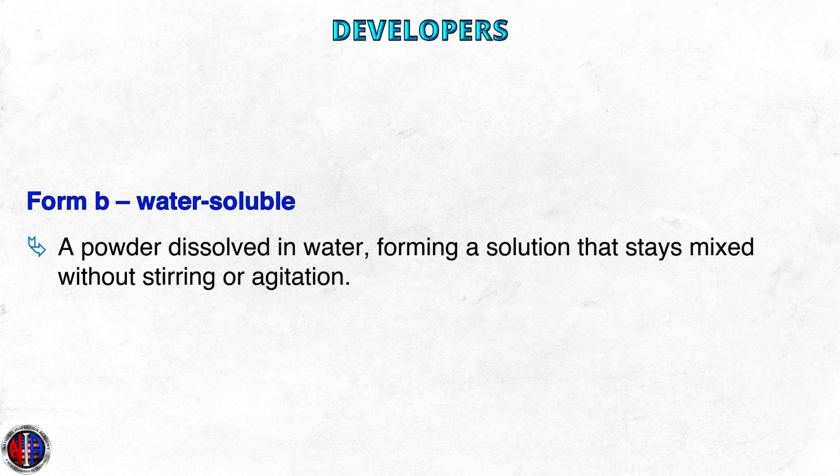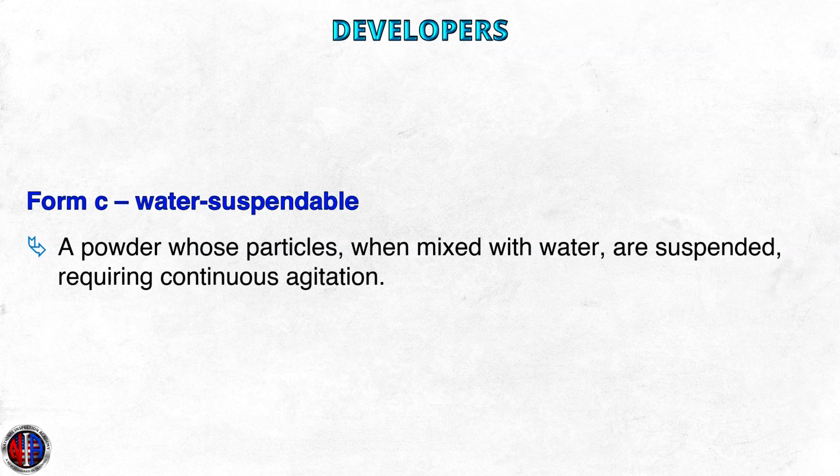Form B, water-soluble. A developer powder dissolved in water, forming a solution that stays mixed without stirring or agitation. Form C. Water-suspendable. A developer powder whose particles, when mixed with water, are suspended, requiring continuous agitation.